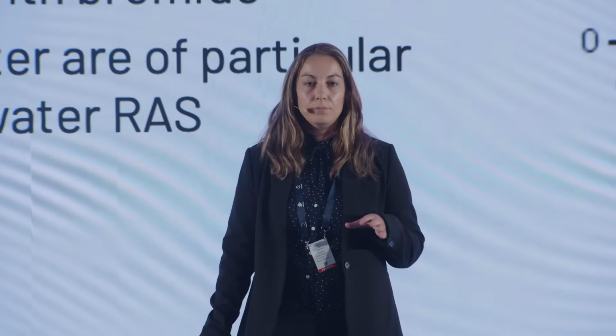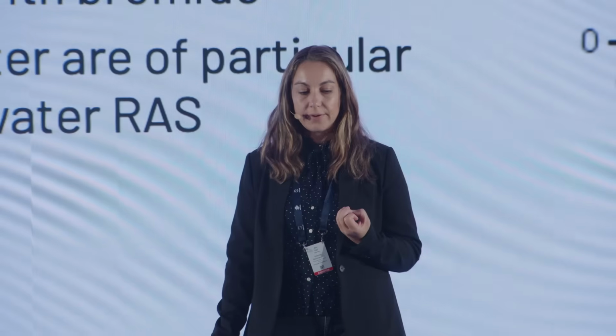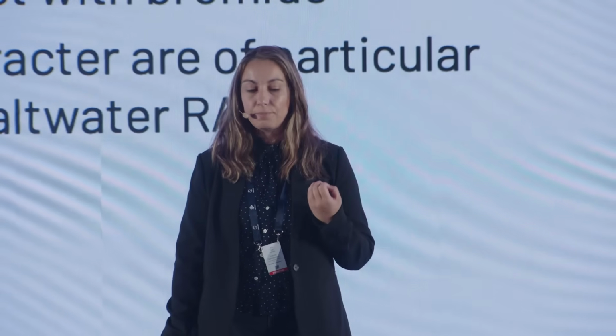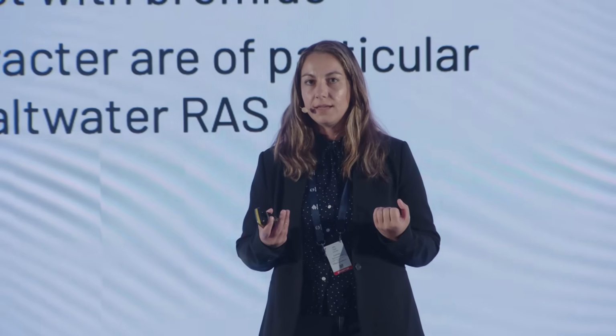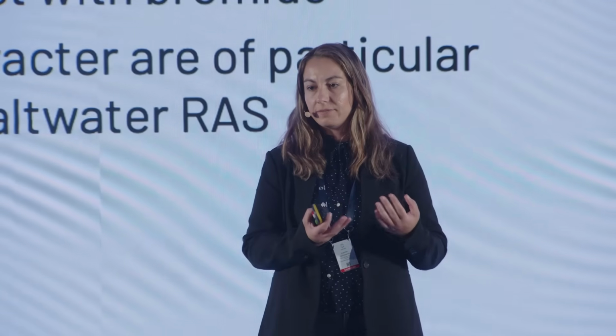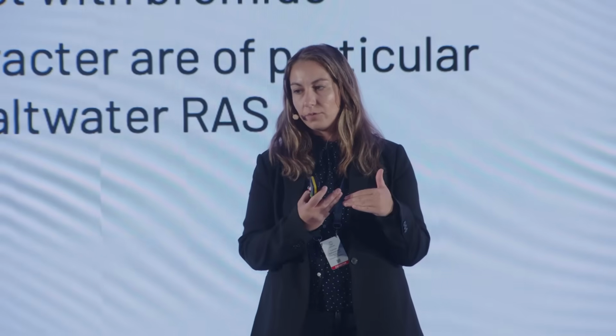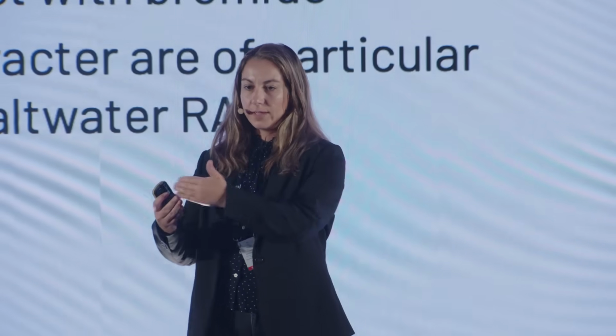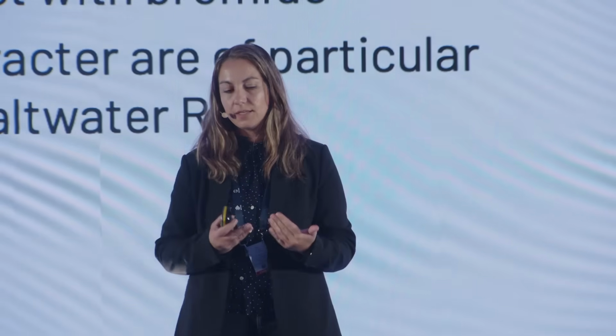It's very important to say that the level of the organic matter that is present and its character play a very big role in the potential formation of hypobromous acid, because the ozone, let's say, is lazy. It will react first with the easy compounds, that is usually whatever has carbon, and when the carbon is gone, it will start reacting with whatever is left, and in that case, bromine, and then it will start making the byproducts.